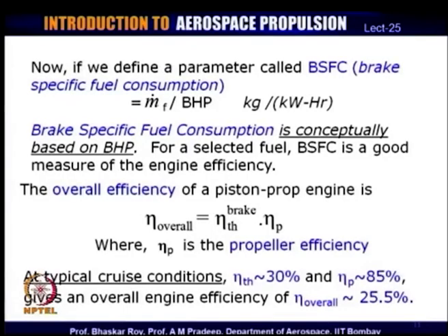So, quite often in the engine specifications, you may not find the value of engine efficiency actually mentioned anywhere. It's more of a theoretical understanding by the designers, but the engineers and operators quite often would use BSFC as the measure of the engine efficiency.